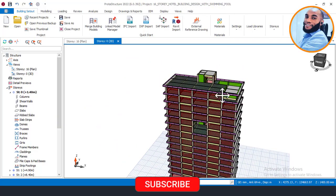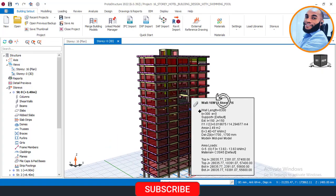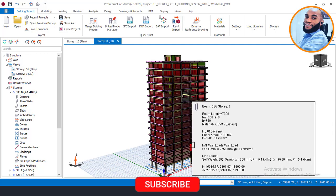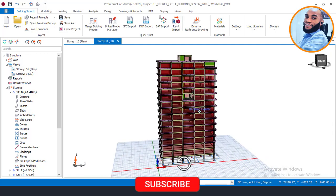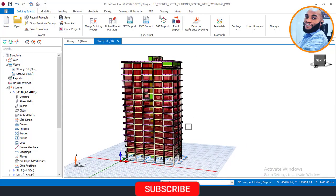Now let me just take a glance at everything that is done on this 16-story building from part 1, for the people that are just coming new. So we started this 16-story building from the CAD file where we did our structural framing or the GA drawing, where we positioned our columns and framed the structure, did our paneling, and also arranged how our beams are going to run. And then we imported that CAD file, which is the DXF file, into the software here and began to model our structure.